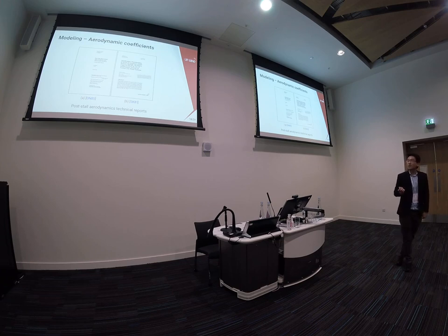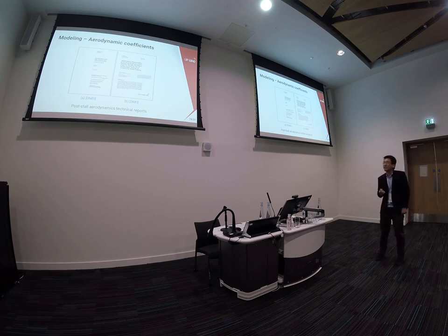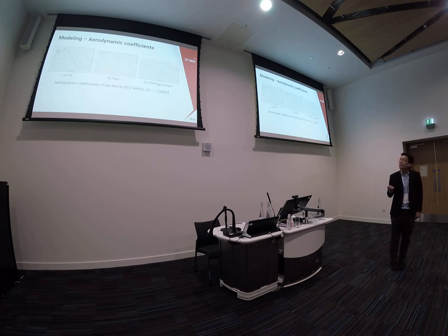There are two popular reports from NASA. One is the post-stall wind tunnel data for NACA four-digit airfoils, and the other one is the aerodynamic characteristics for a symmetrical airfoil. I opened one of these reports, and we see that for the lift force, the small angle of attack regime is a linear function.